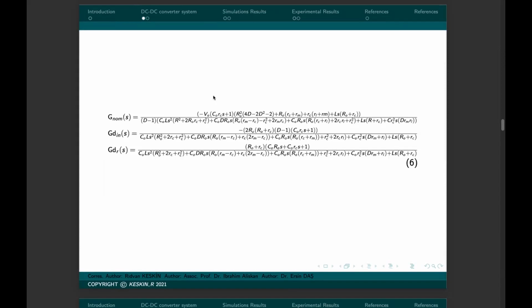Normally, in all of the buck boost converters, and I'm working especially on buck boost converters, all kinds of power converters, I fix the frequency and only change the duty cycle based on the change of the input voltage or output loads. But it seems in your paper you are changing the frequency. No, I use fixed frequency PWM signals.